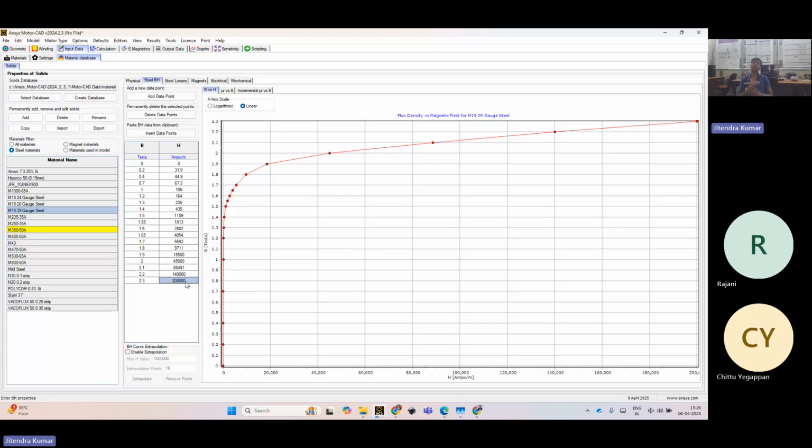And 50 times means how much will the copper loss increase? Like 50 squared, so that will be 2500. So the copper loss will increase by 2500 times. So here you will see the importance of material, what material you are going to choose. Right. And nowadays, at least in a stator, people have started using cobalt-based alloy.